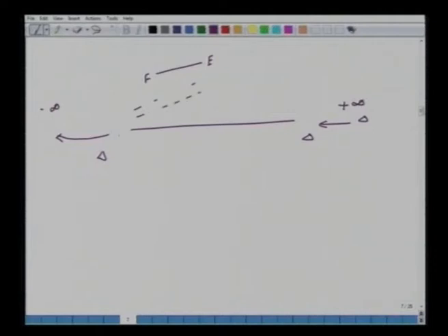Now coming back to the question, for this actual S equal to 2.3 kg per second, how many stages are required? So once we locate xm, from xm we locate the location of E1, then we locate del operating. Once you have del operating, you can construct the stages to find out how many stages are required. So for the last time, again we draw this equilibrium curve like this. You had F 0.5, and then here you have 2%, 0.02. This is pure solvent.